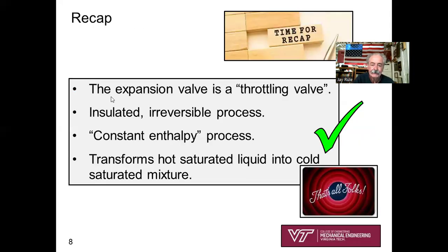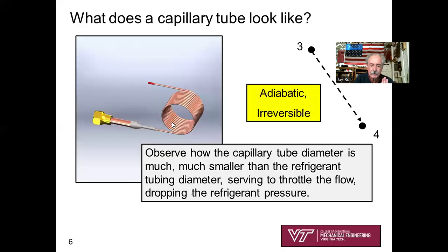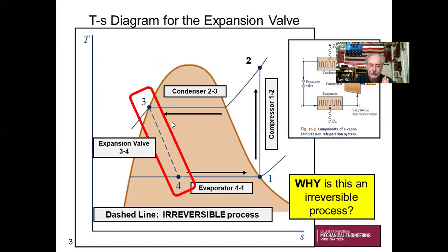Wow. And let me go back a little bit. Something just came to my mind, and then we'll do the recap. I'm going to go backwards. I'm going to keep going backwards until I get to a T-s diagram. There we go. That was a point that I don't think I made in a slide, but I can do it in words. Let's look at our process 3 to 4. And we just showed by the first law that h4 equals h3.